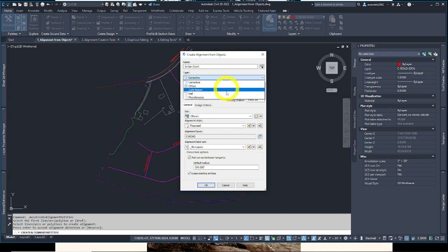Let's verify the type of alignment. Is it a rail alignment, miscellaneous? Is it a curb return where roads hit other roads? Is it an offset alignment, which a lot of times you will make offsets from the center? No, it is a center line alignment. And we'll start at 0, 0. We'll verify that for the site, no site is selected. We'll learn more about these later.